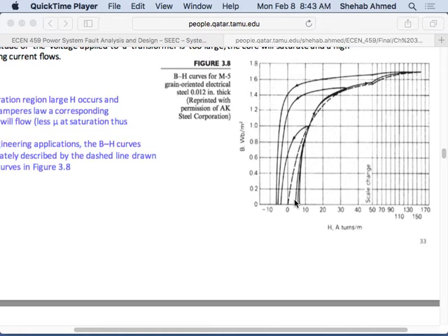Similarly, the magnetic lamination materials are very similar. Fine, they don't maintain a very high value of magnetization, but there is some residual magnetism. If there is some residual magnetism and you run the transformer, initially there is no back EMF generated across the windings. If you're starting from zero magnetization, you have all of this to climb. When you put voltage, which will lead to current, you'll be climbing the BH curve, right?